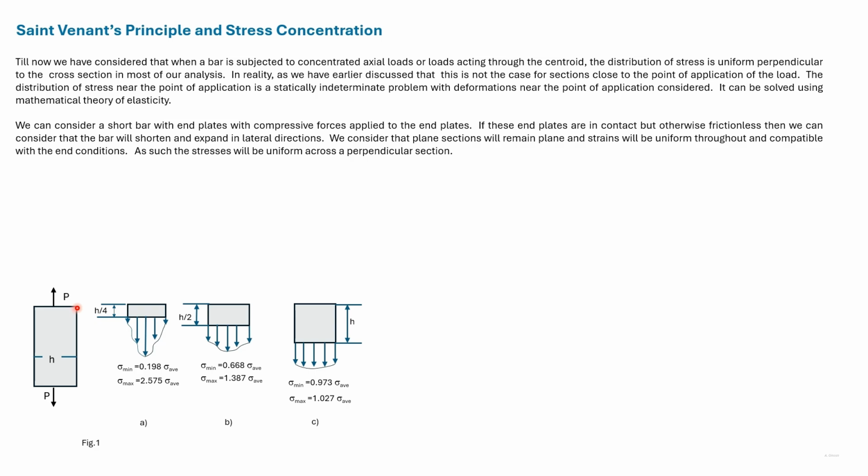For a start, we can see that the deformation where the load has been applied will be much larger and the deformation at the corners is zero. Now here the adjoining elements must be continuous in their deformed shape. Elements will deform by equal amounts on adjoining sides.